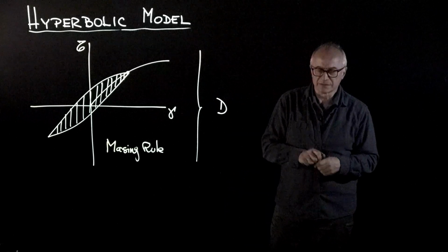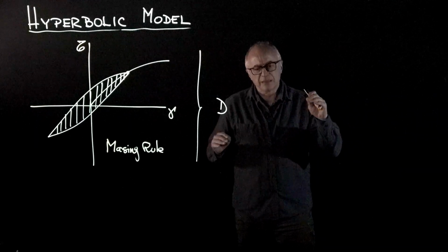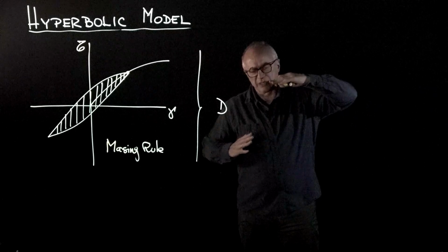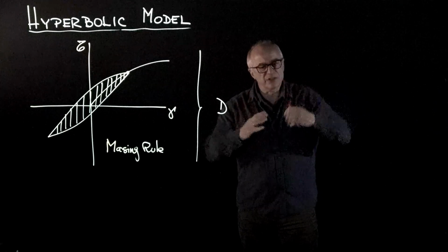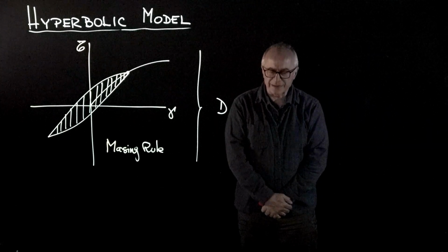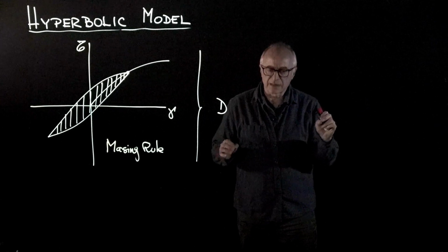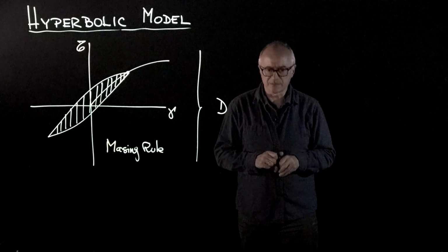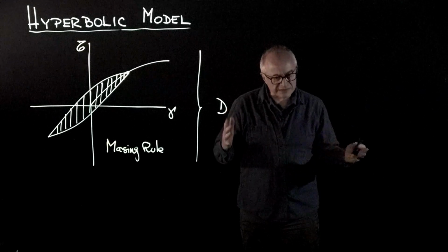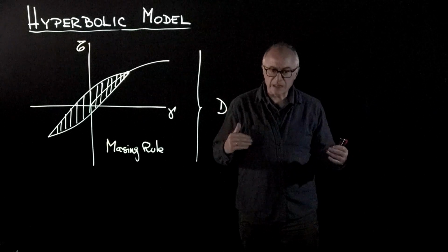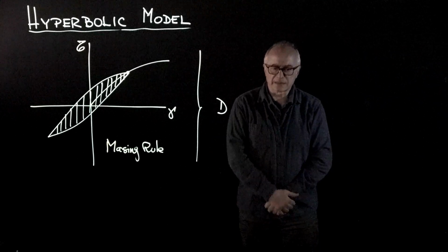In conclusion, if you are not too concerned about all the details, models that capture the asymptote at the smallest strains and at largest strains failure are sufficient for a large number of engineering analyses. And then we can begin gradually adding more details. The hyperbolic model is a case in point, and it can show us two things: the degradation of the stiffness with the strain, as well as the energy consumption in causing these strain levels.